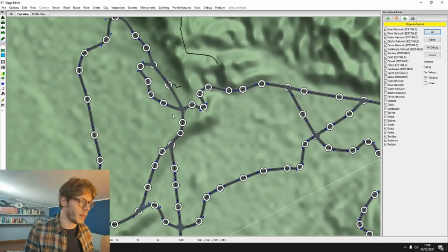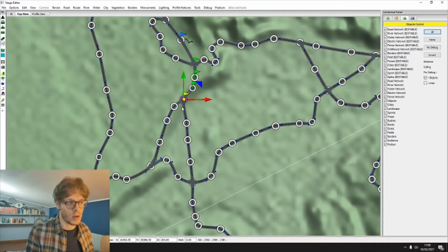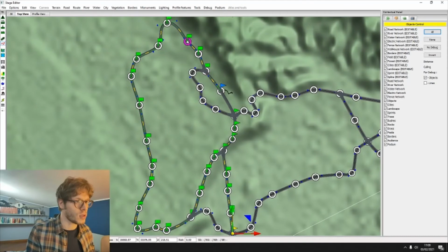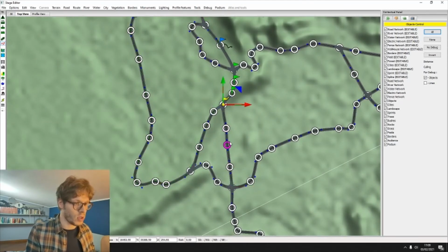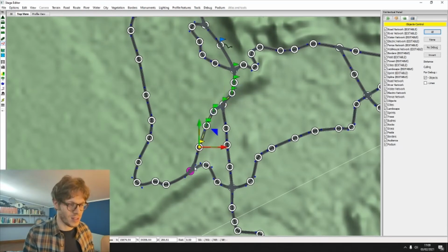I try to see the beginning of our GPX, which is here. I select this feature, and now, like before, with the right click, I start selecting. I can select each point. The important thing is that I can jump some points, but I must select the point when there is a crossroad. If I do it like this, I have a problem because it's automatic and it selects all the roads around. What I must do is select each point. Well, this is no good. This is my problem because I created a road that is circular. So I must do this.